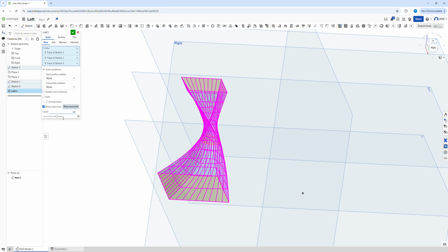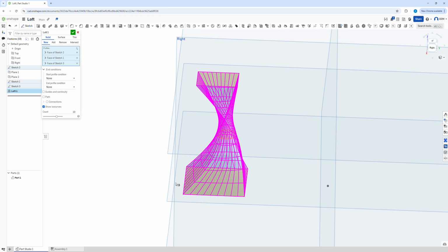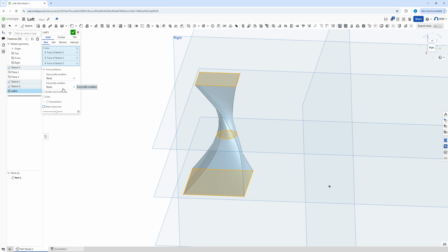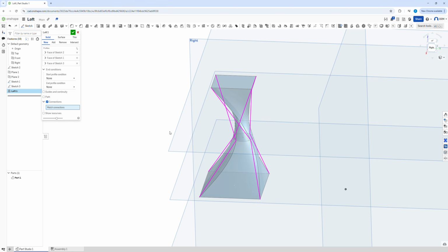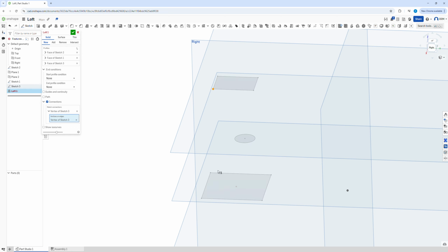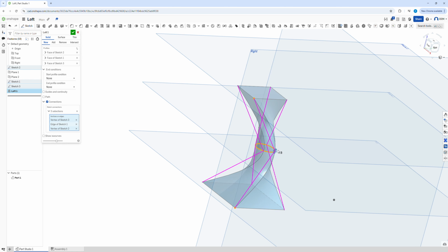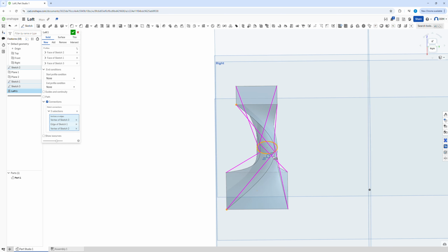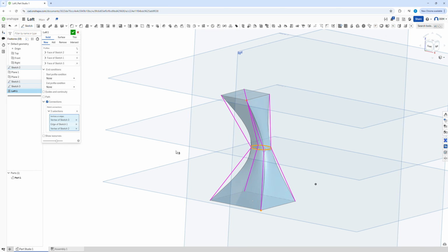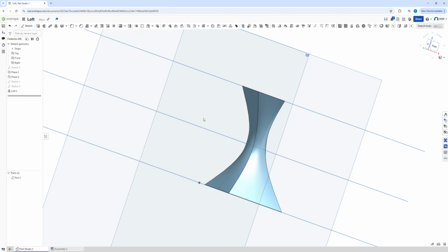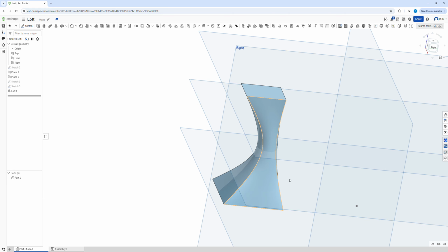So in terms of understanding how this is working, we can see that this is kind of curving around quite a lot. So looking at your connections at the moment, this is all quite twisted. So we can match connections by clicking on here, and clicking on here. And then we can basically rotate these around. Oops, it's a little bit better. So I'm going to rotate this more till it's actually matched up. So you can see there, that is how we want it to be set up rather than how it was before. Okay, and then we've got our lovely loft, quite organic, quite interesting shape.